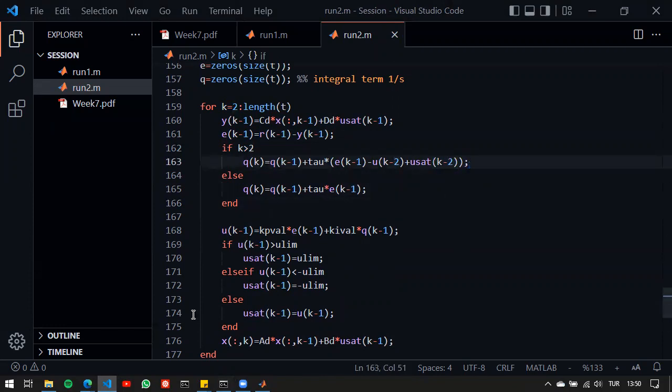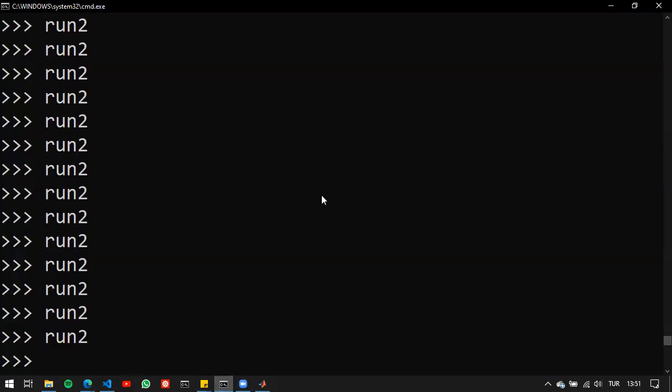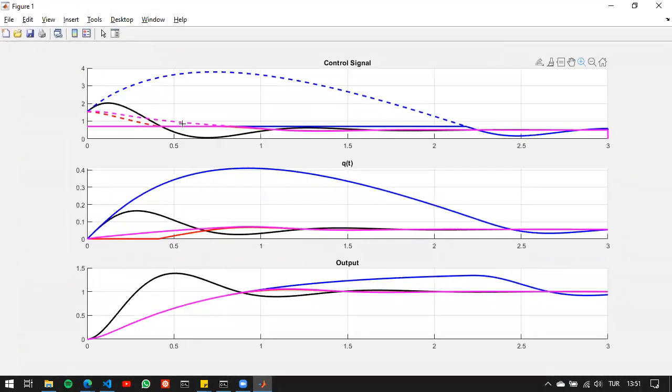Now let's see. Yeah. Now let's assign us another color here. Let's use magenta. Now, of course, it gets a little bit crowded here, but we can see that that also solves the issue here, which is a bit different because we have a delay element and then we are basically subtracting the difference from the control signal from the error itself.